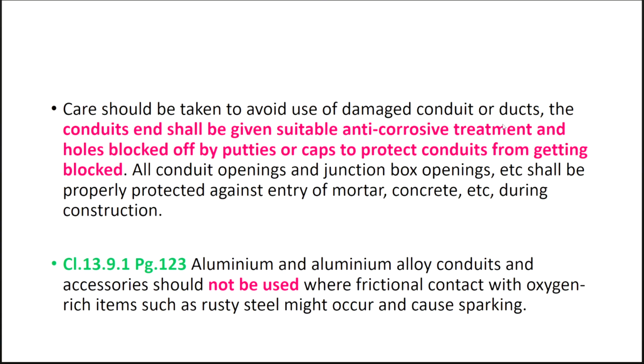Care should be taken to avoid use of damaged conduits or ducts. The end of that conduit shall be given suitable anti-corrosive treatment and holes blocked off by putties or caps to protect conduits from getting blocked.